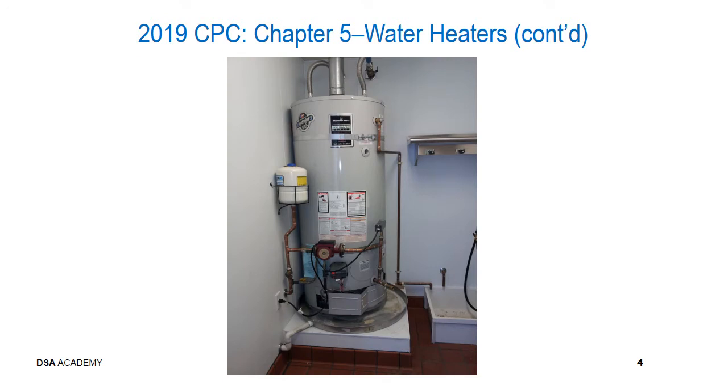This image of a water heater basically shows the strapping requirement for strapping a water heater, protecting it against a seismic event, where you can see there's straps on the top third and on the bottom third, and the bottom third strap is generally around 4 inches away from the controls located at the bottom of the water heater.